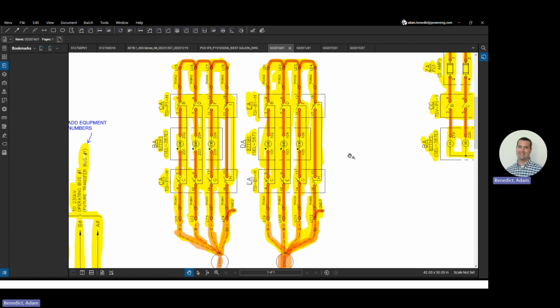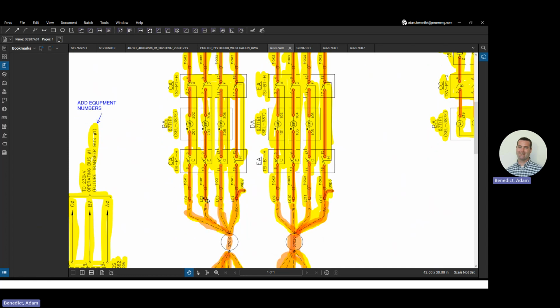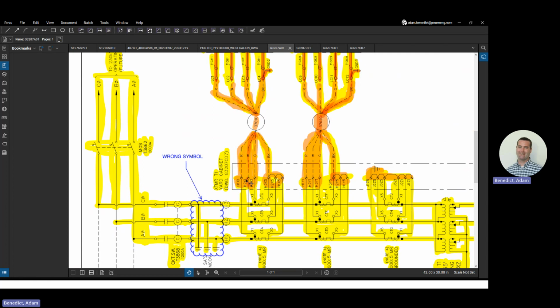But where they don't use, these are shorting terminal blocks down here. So this utility would have just regular terminal blocks, and a shorting terminal block. Let's see if I can get you a picture. They have these screws to help short out the CT. You would put a screw between 1 and 5, and once you connect that, it automatically connects the ground.